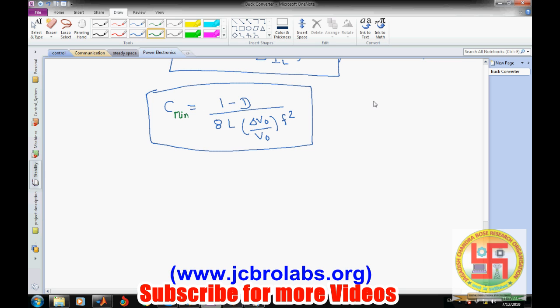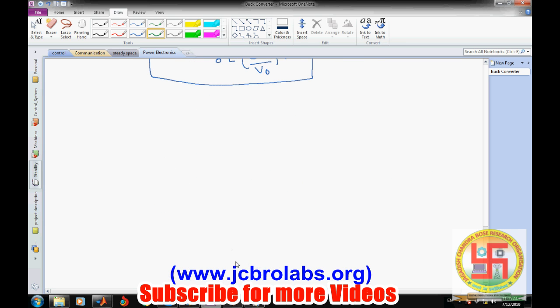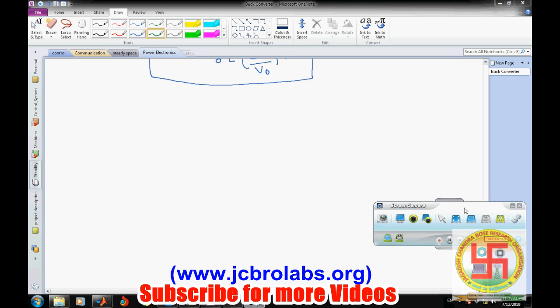That means if we want a certain ripple, we can have any value of C which is greater than C minimum. That means C is greater than or equal to C minimum. But this much C is required if we want a specific amount of ripple in the output, and we will see this in the simulation as well. So this is for the continuous mode, where this relation holds good. Our main requirement is that this buck converter keeps working in the continuous mode only.